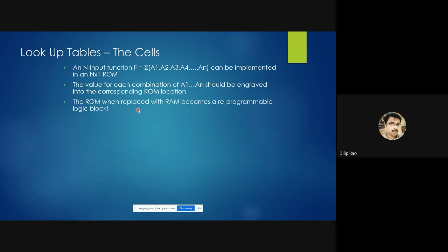Okay, so this entire lookup for any combinational circuit that you want to implement will be translated into a lookup table, and that lookup table will be stored in the memory elements of the FPGA. That memory element of the FPGA could be ROM. There is no, so to say, ROM in an FPGA. All we have is basically a RAM. You can realize a ROM, but at the base it is just a RAM with no write port. That is what we call a read-only memory. No write possible, but it's called a read-only memory.